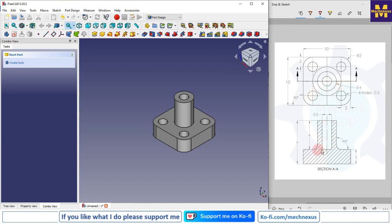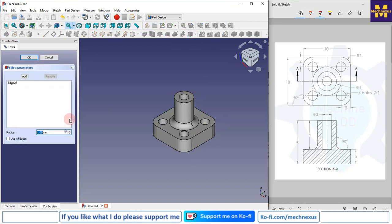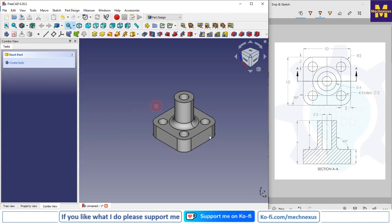And from here we will give the fillet. If we see in the section view, the fillet is not given, so we will take some approximate value for the fillet. So here it is 1 mm. Say OK.